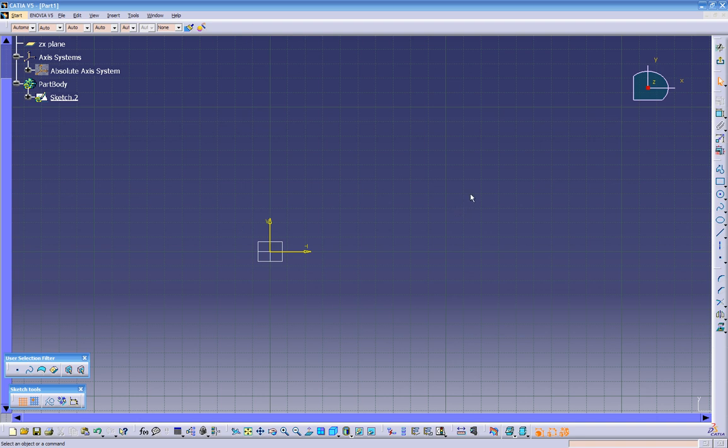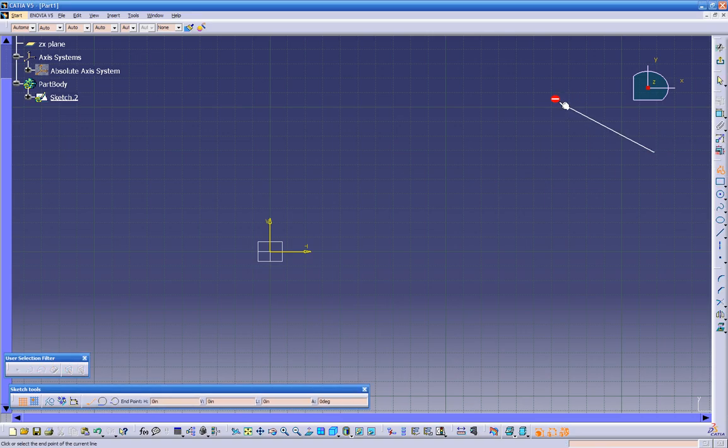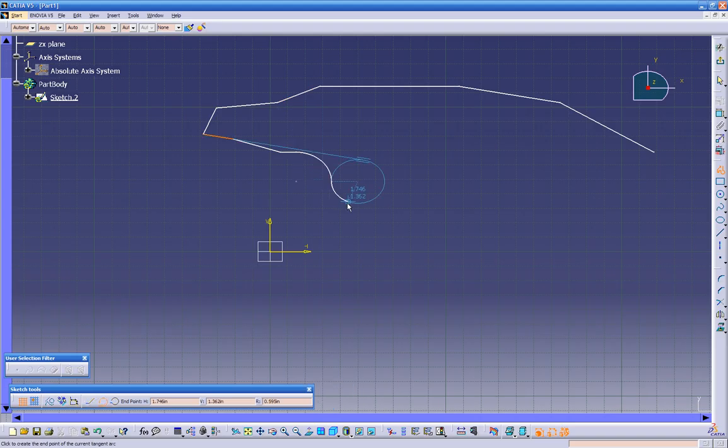So we can create just a quick rectangle. Click on the rectangle. You see we have quite different options over here we can create. It's a profile. This will create multi-lines. If you just snap it, you can create a line. But if you snap and hold it, it creates an arc. So snap and hold, then a quick tap goes line, line, line.